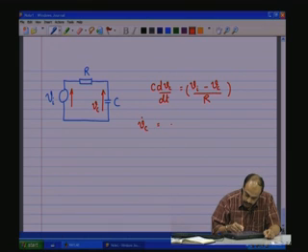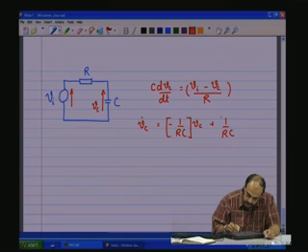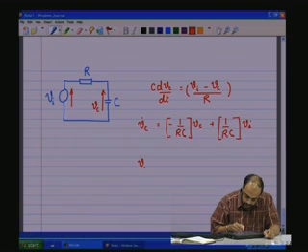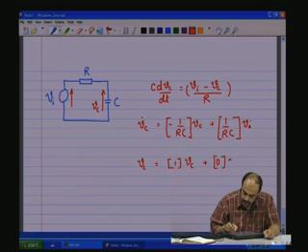Or putting it in our standard form, Vc dot will be equal to minus 1 by RC into Vc plus 1 by RC into Vi, and let us say V naught is our output, which is given in this form, plus 0 into Vi.